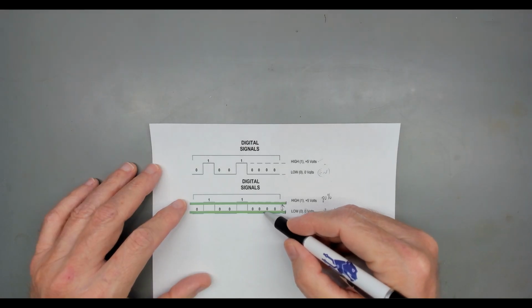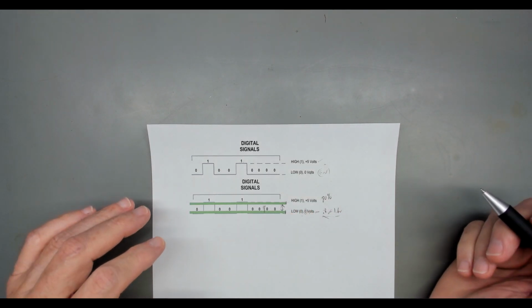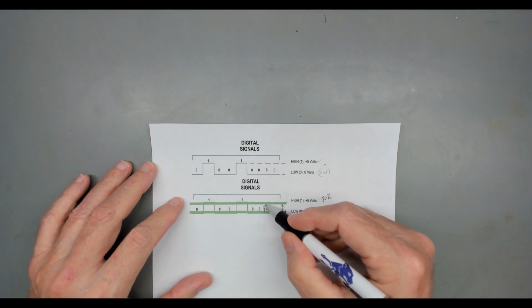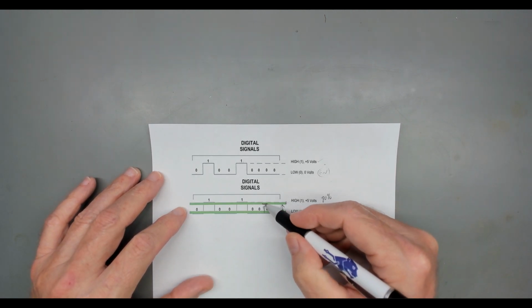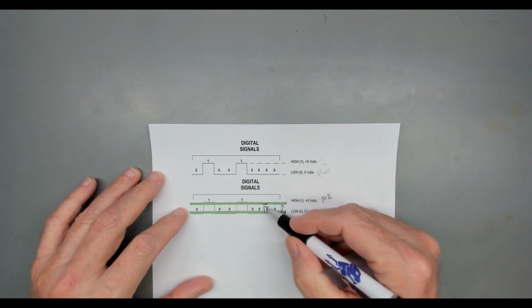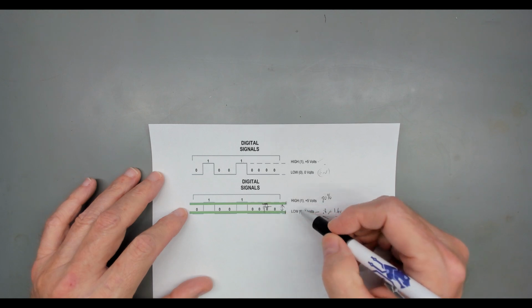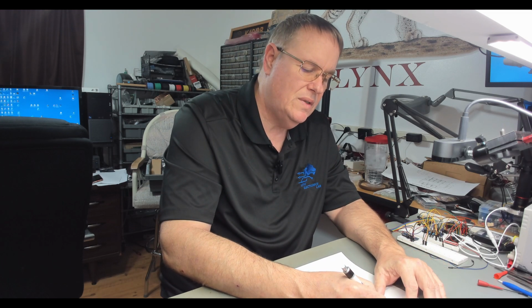If I'm 0 and I start going up, I'm going up here, and I'm in this range, I'm still 0. If I was 0 before, I'm still 0. But once I break this line right here at the bottom of my range for high, I'm going to change states to high. Now, if I was to dip back down in this area, I got up and became high, and then I dipped down below this, I would stay high until I got down to the top of the low level, in which case I'd change states. Now, why is that? Well, this is called hysteresis, and I probably pronounced that poorly. As y'all all know, I speak one language, English, and I don't do that exactly great.